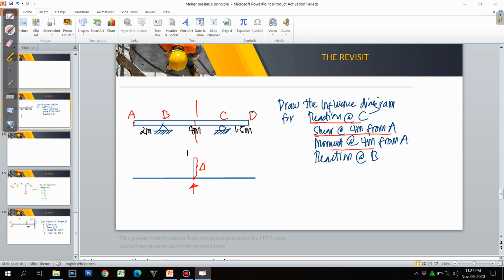And this is pin connected here, and there will be a roller here. So if we push that upwards, your left portion will have a downward displacement at A, and it will remain at point B. So it will stay at point B.